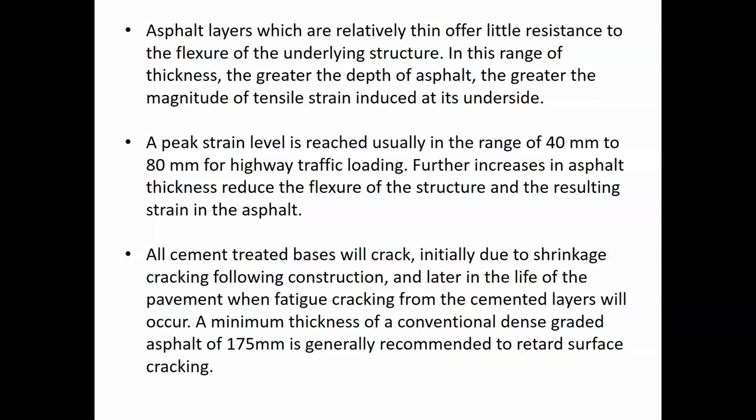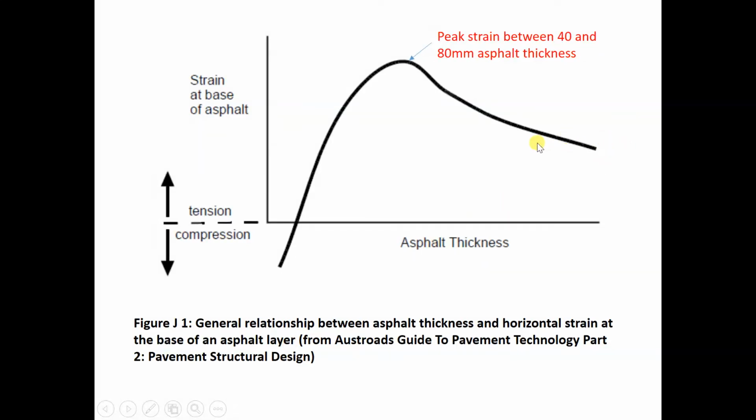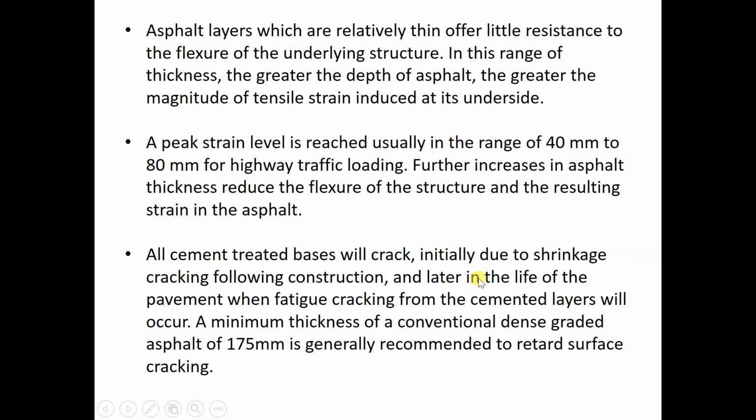But if you have 175 mm, probably somewhere here, the tensile strain is probably less at that point. So when you use thicker asphalt, it will retard the surface cracking. The chance of cracking is less because the tensile strain is lower at the higher thickness.